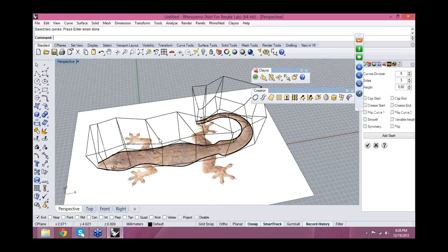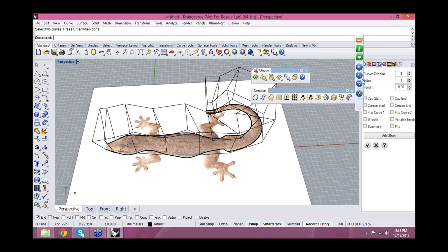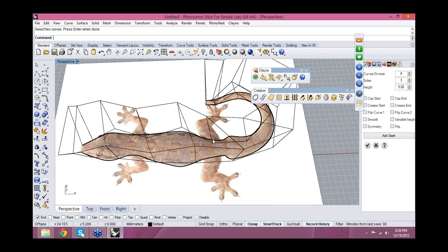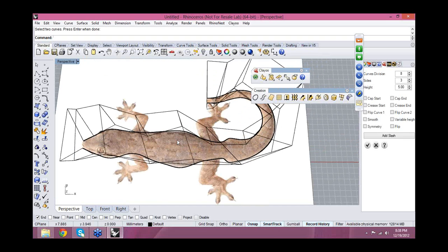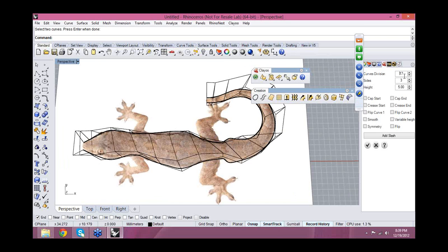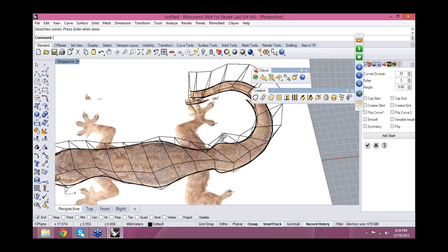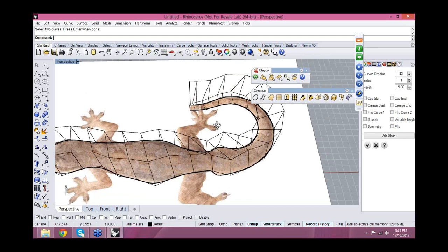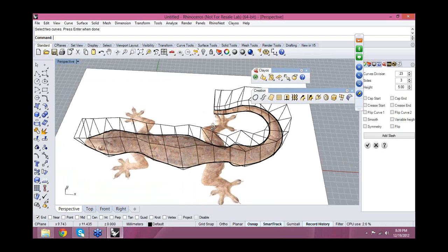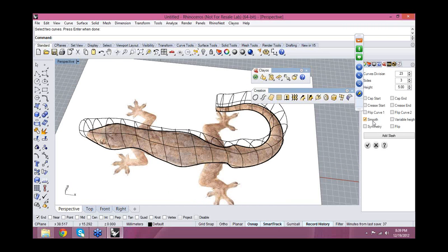Basically here we have options, curve divisions. In this case, by default this tool creates the surface with 8 divisions, but this is not good enough, and probably we need to add more divisions. We have the same problems as if we create a sweep in Rhino: the ISO curves are not very good. Then the idea is, well, first of all, we define the height. Let me show you in the smooth view, and I will change to shaded.